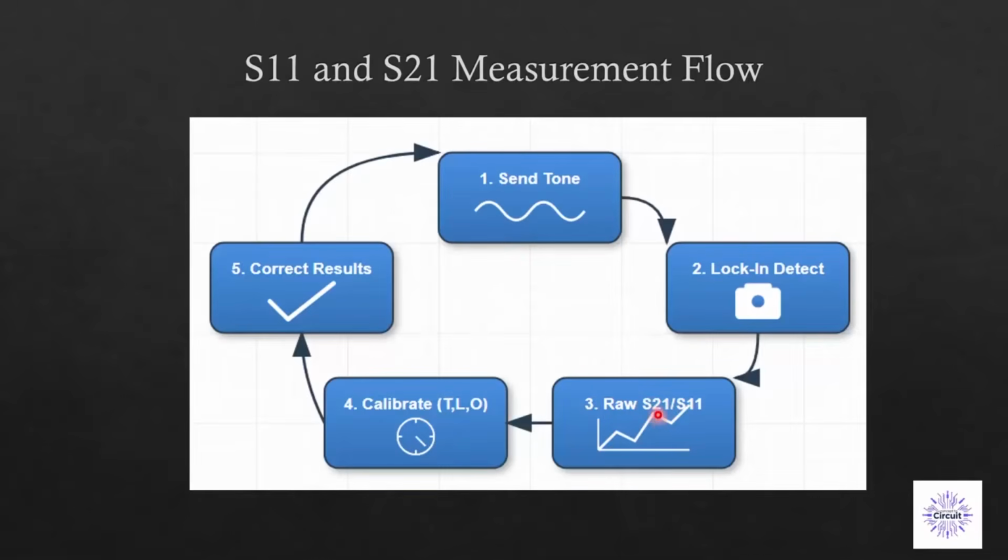For calibrating S21, as we saw, we needed a full calibration, meaning that instead of a device, we just put an adapter that connects input to output with a gain of 1, so we can calibrate whatever loss we have in the cables and then cancel it from the measured S21. Also for S11 measurement, we need calibration when the whole wave is reflected back or none of it is reflected back.